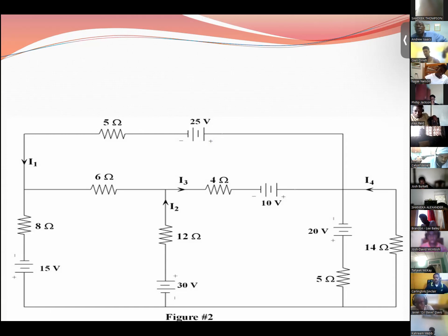If you put a different resistor in the circuit and recalculate from scratch to find the current, and if you simply put that resistor now connected to the Thevenin, you'll get the same answer. In other words, you can vary the load. It won't affect the answer when you look at the complete network.